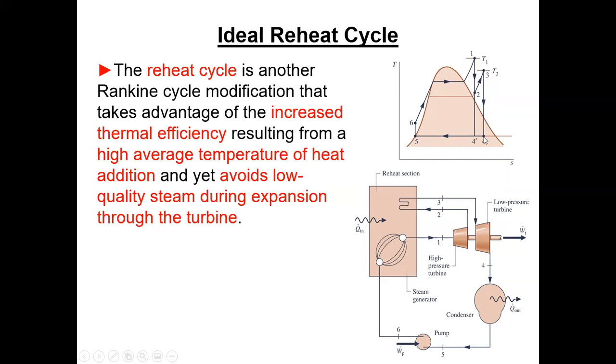And so, well, that does a couple of things, right? It increases the average temperature of the heat addition, because now instead of just heating here to here, we come back and we're going to do this little whoop-de-doo in here, which is at fairly high temperature. So that's going to increase my average temperature of heat addition. And instead of coming out of the low pressure turbine at 4 prime, I'm going to come out at 4, which means I have less moisture. So the reheat is a win-win. I've got superheat helping me, and then I can add reheat that can help me further.